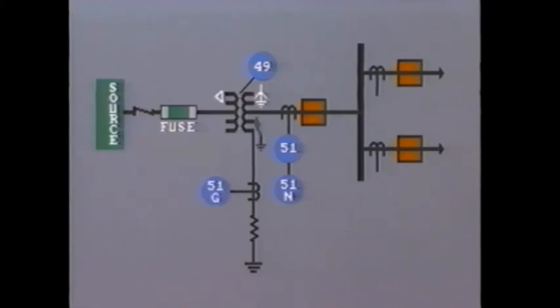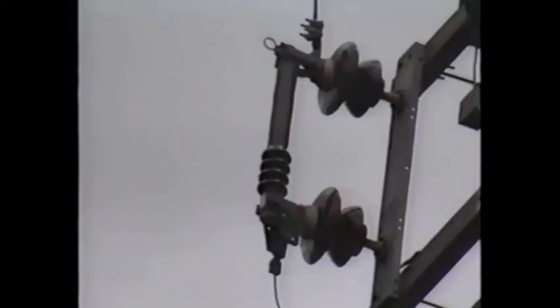As we mentioned before, a low-level ground fault on the secondary side may not be sufficient to blow the fuses on the primary. In fact, these fuses may not even blow for a ground fault on the primary, as the delta winding is ungrounded. The real function of the fuse is to protect the primary windings against a heavy phase-to-phase fault within the primary winding. But a small fault or perhaps persistent overload could go undetected and eventually damage the transformer winding insulation.